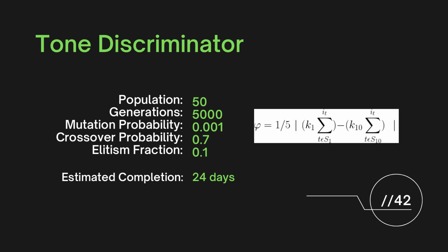The output from the FPGA in the presence of a tone is integrated into the op-amp, which is then read as either a 1 or a 0 by the microcontroller before being reset in preparation of the next tone. Fitness is determined by summing each set of sampled frequencies independently, then taking the absolute difference of the two sets. The maximization of this difference yields a better discriminator.